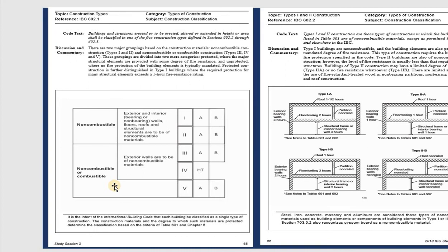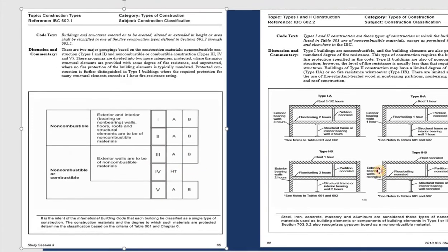When you select any type of construction, you need to show it on the title sheet to make sure that the plan checker in the city knows what code you use, and they focus on checking that for you.